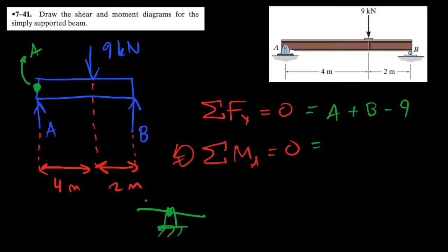And if I get on top of the seesaw and I press down with my hand, obviously the seesaw is now going to a position shown by this dotted line. The seesaw will go like this if I apply a force. Now, similarly, if I apply a force here, then the seesaw will be in this dotted line. That's the sort of approach we can apply to the beams, because we clearly see that our convention depends on whether the beam is bending clockwise or counterclockwise.